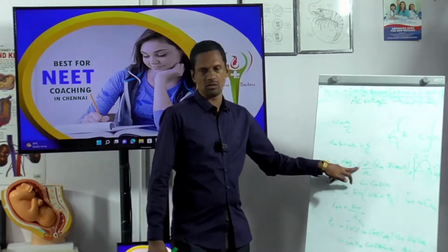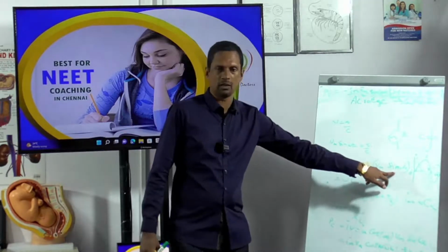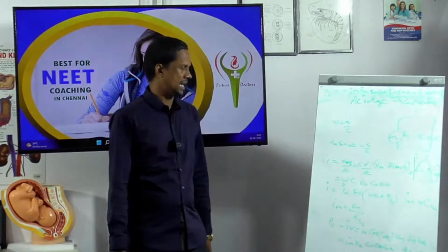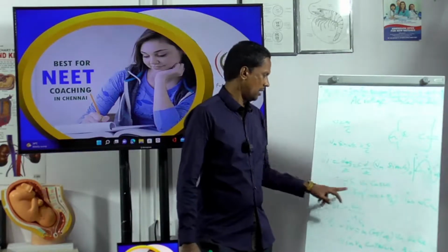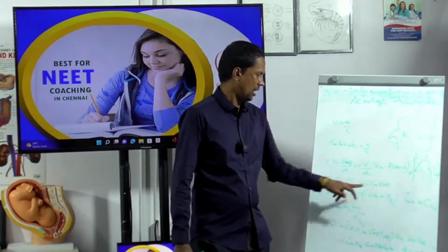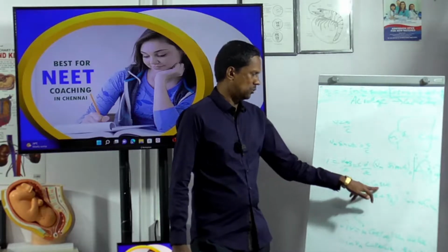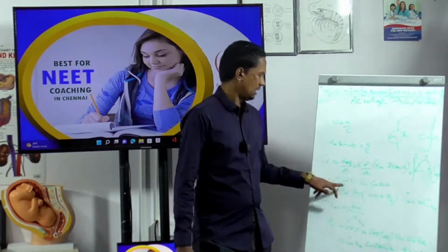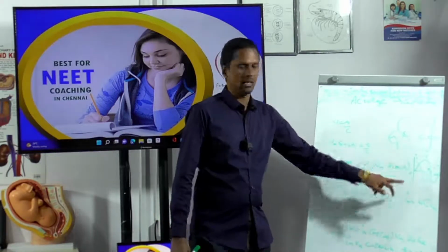C is a constant value, so we take it outside. So C into d by dt of Vm sin omega t. The differentiation of sin omega t is cos omega t, and the differentiation of omega t is omega. So with C constant, I get omega C Vm cos omega t.